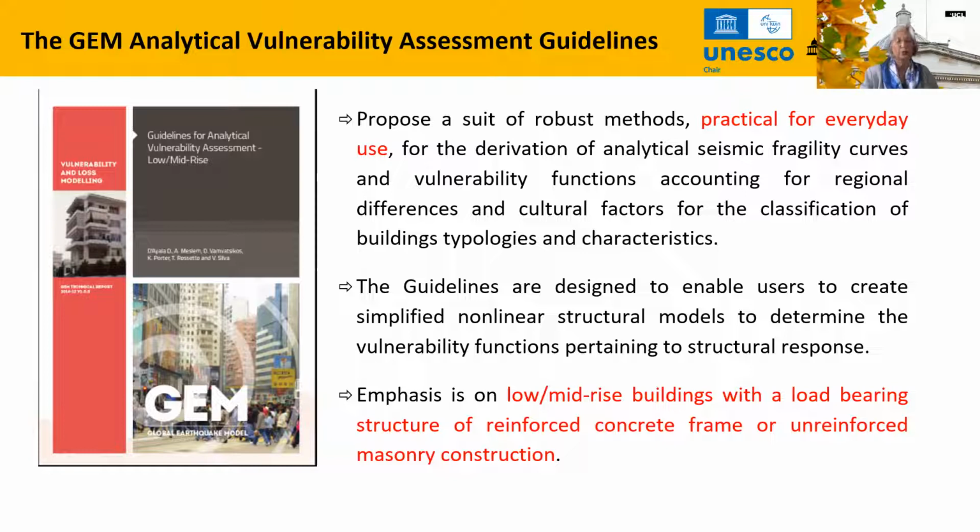The guidelines, which were developed and designed in 2015 within the Global Earthquake Model framework, which is still ongoing and which you can access at GEM online, are designed to enable users like you to create simplified nonlinear structural models to determine the vulnerability functions pertaining to structural response.